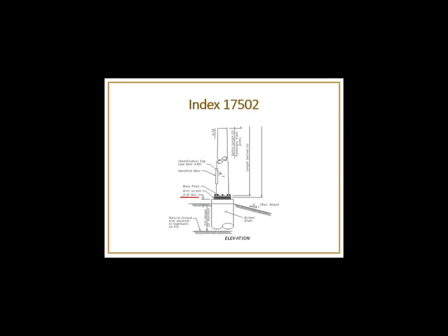Now, if for some reason the designer didn't pay close attention to where that shaft was and put an elevation down there, that elevation might not be 2 feet above the existing ground. Another reason might be that it had to be shifted in the field due to utilities or some underground conflict that was not shown in the plans.